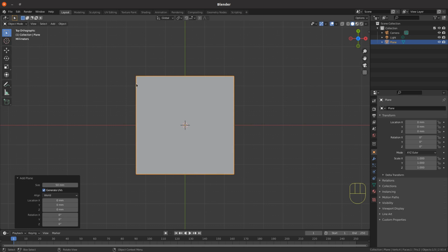The two sides of the plane, the left and across the bottom, will now represent the outer edges of the angle iron, but the rest of the face isn't of use. But we don't have to destroy that and then rebuild edges and faces. We can modify the shape of the plane by adding vertices.